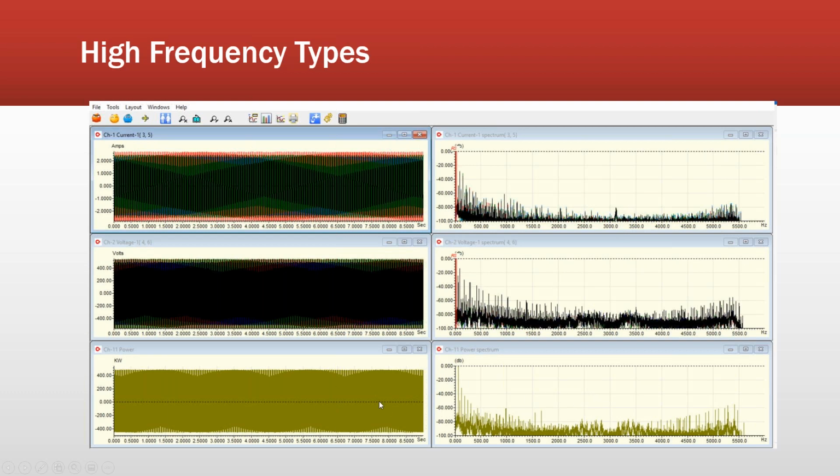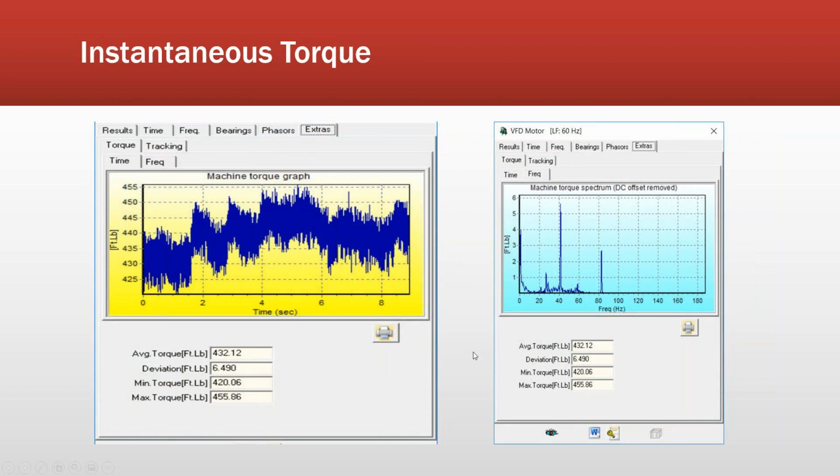I normally don't look at this in dB because in power, it'll actually show up as kilowatts. And when I convert it back over to linear kilowatts, the peaks are exactly what I'd calculate in vibration and relate to the losses I'm looking at for that particular defect. I use that on the commercial and industrial side: if we see, say, bearing defects or misalignment or some other condition, we can identify the energy loss due to that frequency and the related greenhouse gas emissions.